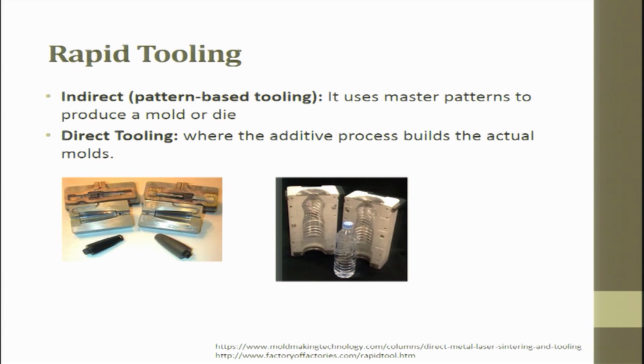So, here you should understand, we are trying to make a product, this is a product. Here we need a tool, and then again for making this tool you need one more tool, which is called indirect tooling. What is direct tooling? It is directly producing the given output.